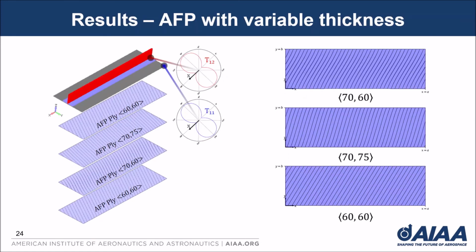Here is an exploded view of the optimized AFP skin layup. Only one ply of every balanced pair is shown for simplicity. Note that darker regions show the AFP local thickening due to the overlaps. Angle variations between control points at the edges and at the middle section of the unit cell are relatively small due to the AFP constraining steering radius of 500 mm. Small variations in the membrane stiffness are shown in the polar plots in the figure on the left. The resultant skin is a soft laminate, and the stringer provides much of the axial load carrying capacity of the panel.